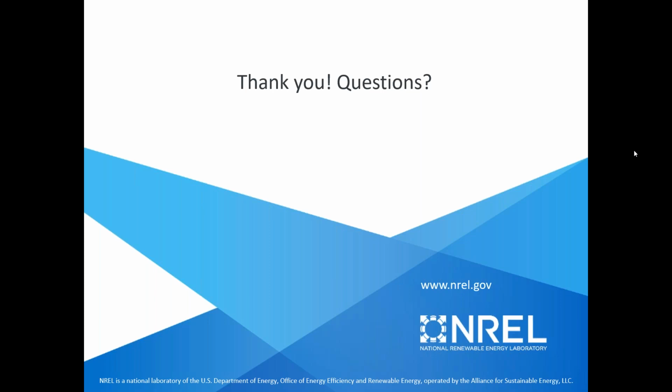Okay, and then the next question is, when we change the MPPT number from 1 to 2, does SAM treat each MPPT as half of the original inverter? Does SAM do it similar to PVsyst, that the MPPT voltage and current parameters are halved? Right, great question. So SAM actually treats it a little bit differently. We model the inverter as a whole rather than as two separate inverters, which is why we don't require the user to specify a split of the power between the two different MPPT inputs.